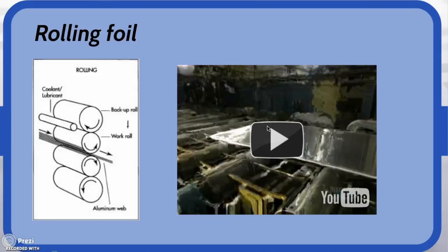the rolling process. During these rolling processes, the aluminum occasionally must be annealed to maintain its workability. The reduction of the foil is controlled by viscosity, quantity, and temperature of the rolling lubricants. The roll gap determines both the thickness and the length of the foil leaving the mill. This gap can be adjusted by raising or lowering the upper work roll.